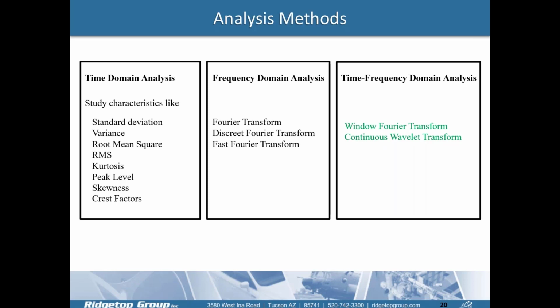The same thing applies to frequency domain analysis. If we apply this method, then we don't have any information on the time. Sometimes the vibrational signal is recorded for a long period of time, like 1 week, but when this bad phenomenon happened, it was on the first day, or second day, or the last day. This is why time-frequency domain analysis is very common, and these days everyone uses either the window Fourier transform or the continuous wavelet transform. But in this work, we focus on the window Fourier transform, and in the next slide, I'll tell you why we chose it.